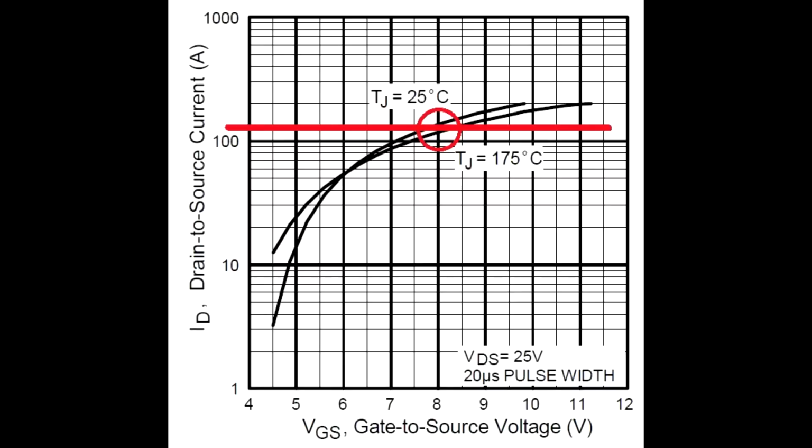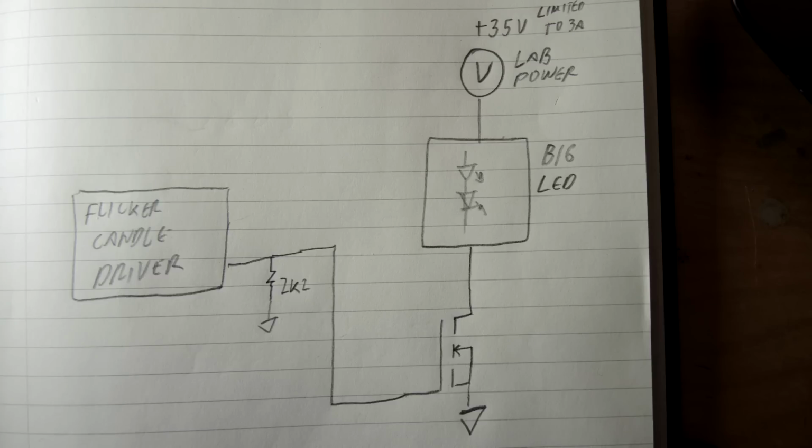Let's draw this little pad here. We've got 2 boxes on the left, of course, the little LED driver that has the flickering effect on it. On the right, of course, the big chunky LED module. Draw the MOSFET in here, and we hook it up. If you notice, there are no additional components required for the assembly, and that's, of course, always the beauty of N-channel MOSFETs. Super easy to use. So let's solder this into the assembly and take a look at what that looks like.